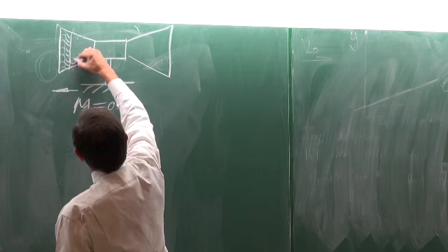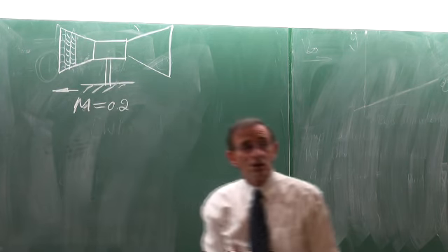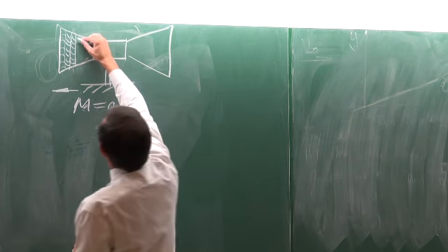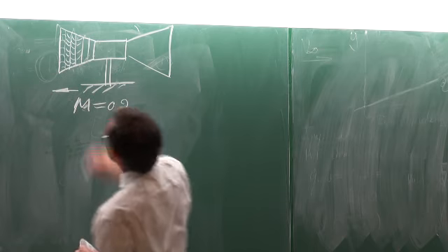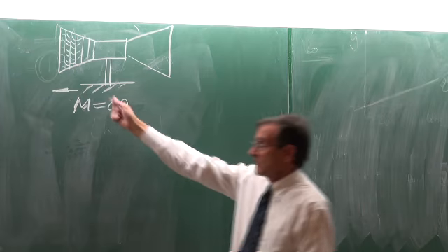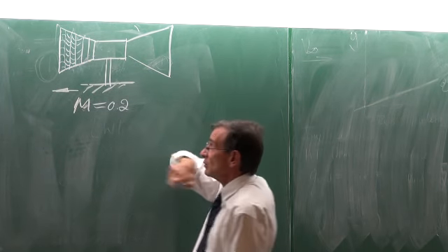And then again, after that, there are some blades again, which are stationary. So they direct the fluid again for the next set of blades. Okay, and this goes on quite a few times. The purpose is to compress the flow. So that is called the compressor. So the compressor, the combustion chamber, and the turbine.